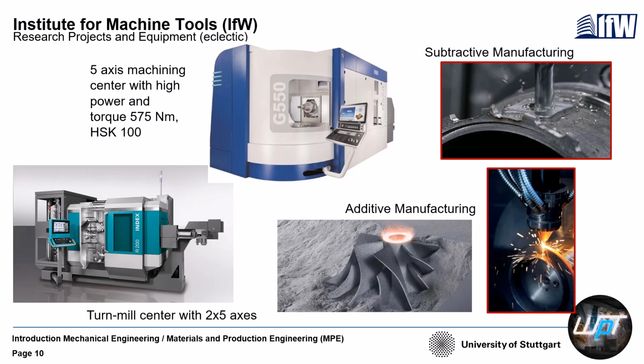A very new trend is to build up, to generate structures, as you can see here with the additive manufacturing picture, but also to reduce or to subtract material, as you can see here, by the milling or boring or drilling process. This is a portion of a workpiece which was previously additive manufactured. So we can apply material to that particular area of the workpiece, but also we can reduce this and just shape new dimensions and new functions into the part.